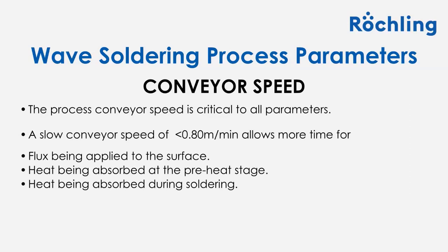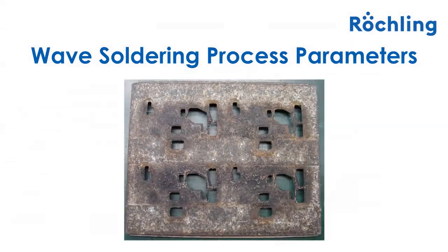result in warpage. Flux is going to remain active for longer due to the build-up and the higher temperatures, keeping it above the activation temperature even when it exits the soldering conveyor. The higher temperatures are going to contribute to burning of the resin on the surface. And all these parameters are going to contribute to a shortened lifespan of the solder pallet.